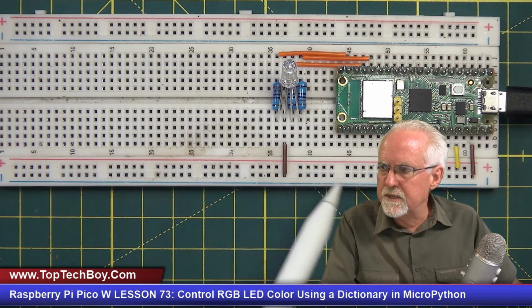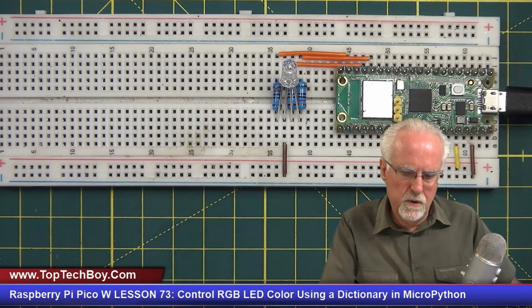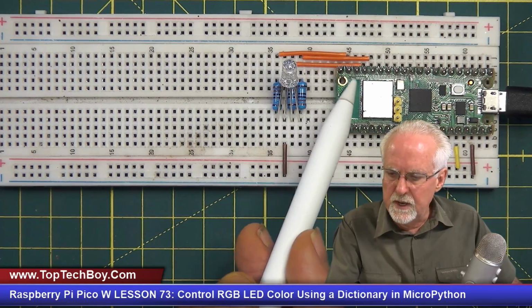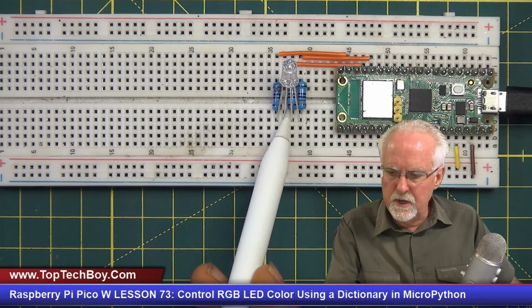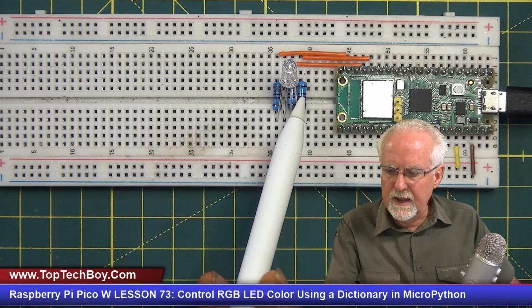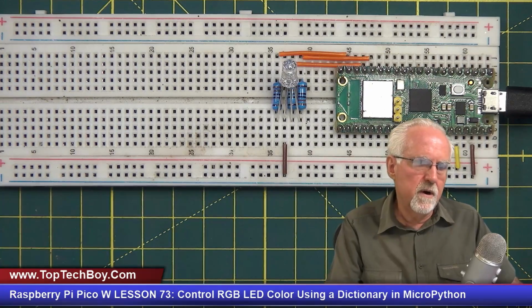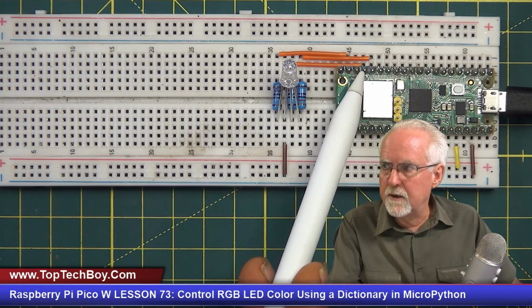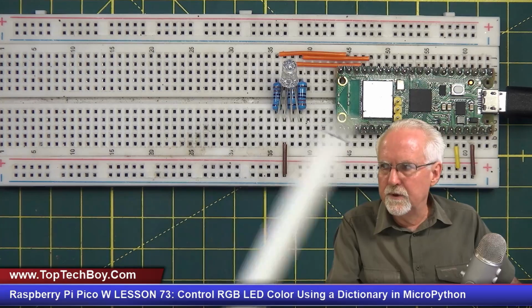Ground, of course, comes down to a ground rail. The R goes through a 330 ohm resistor to GPIO pin 14, and then ground goes to ground. G, the green pin, goes to GPIO pin 13, and the blue pin, the last one over here, goes through a 330 ohm resistor over to GPIO pin 12. So RGB are GPIO pins 14, 13, and 12.